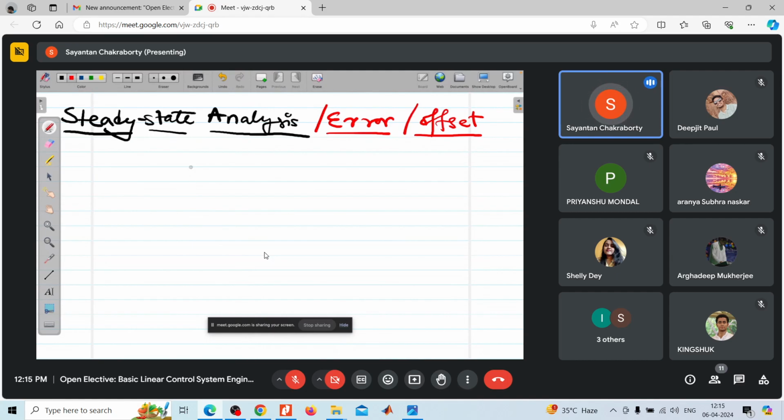Say the reference value was set as 10 units. Now suddenly you increase the value to 12 units, like a step function, from 10 to 12. Now your performance requirement is that if the initial output was at this level, say 10, you need to reach 12, but due to some problem it reaches only 11.8. So there will be an offset. So these are the main causes of the offset: following a change in the input, the system may not be able to follow the change in input perfectly, right? Now, why may this happen?